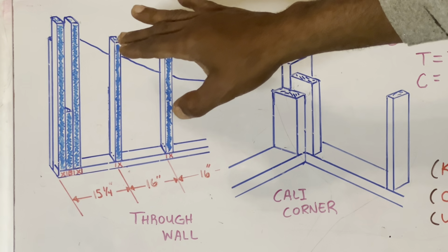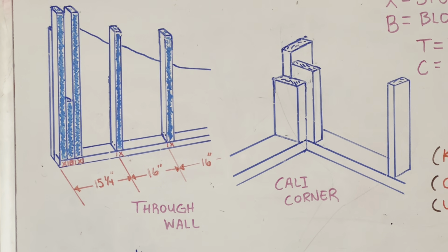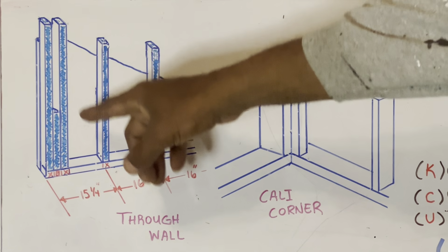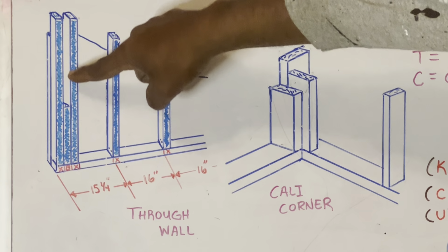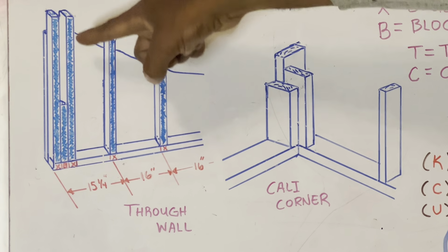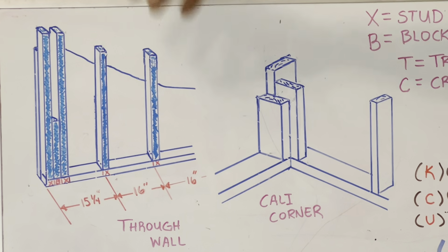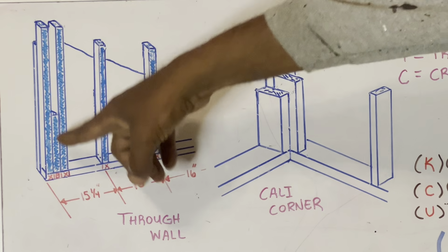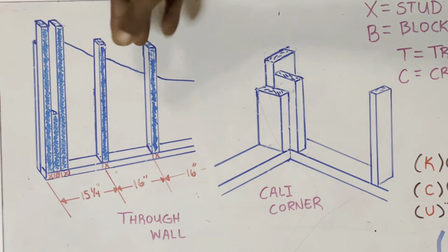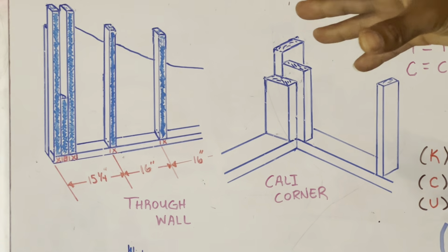So this type of outside corner post, which is basically called 3 studs and a block, leaves a cavity. If you can see right here, see this cavity that's going to be left in this block. Then if you keep on going, you'll go to another block, probably a center block, and then past your center block, you have another end block, just like that. So you've got 2 large cavities, one on each end, where you can't put insulation.